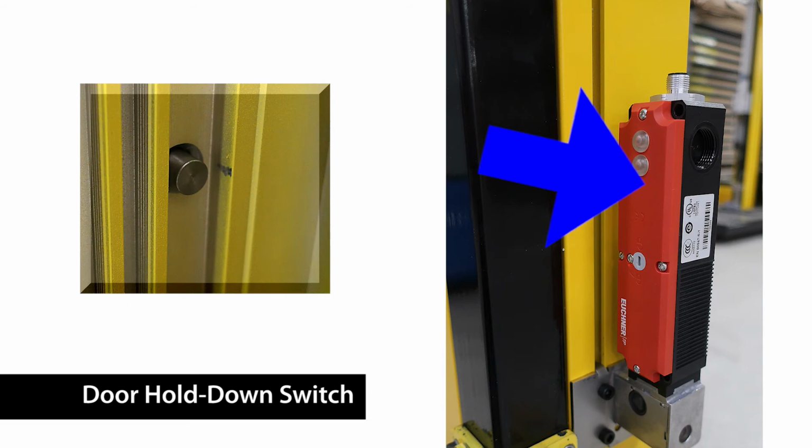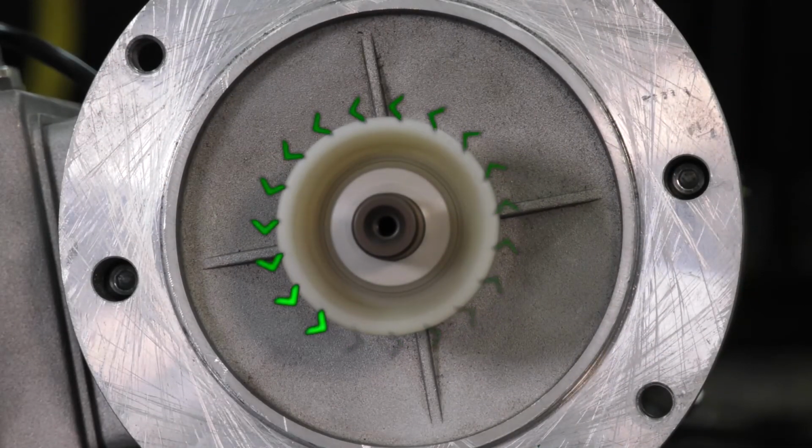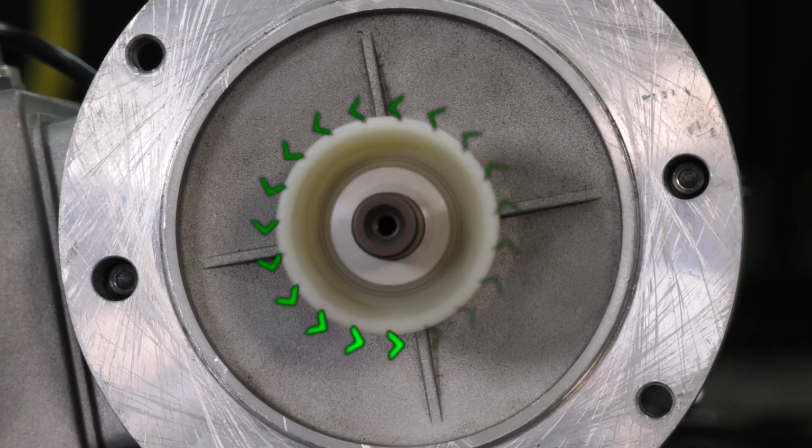The door hold-down switch prevents the door from being manually lifted when the door is closed. It is not intended to be used in place of the door-closed safety interlock. The door hold-down switch control logic is the responsibility of the integrator. The encoder is available on the gear motor if you require precise positioning feedback. It is often used with a variable frequency drive.